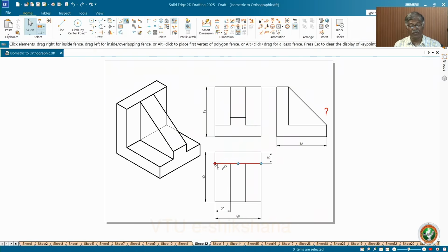Is there any change in the top view? No change in top view, because this is completely a line reference. Okay. This one, line. Again, this is line reference. No change here. Irrespective of the contour, you can see only line. Here, as usual, you get the rectangle and one more rectangle representing the slope. Whether it is up to this edge or above, 20 mm above or 10 mm above, one and the same. Because it's all coinciding. These lines are all coinciding. That's why you will get same thing. So top view is same thing, and this contour you get in the front view.